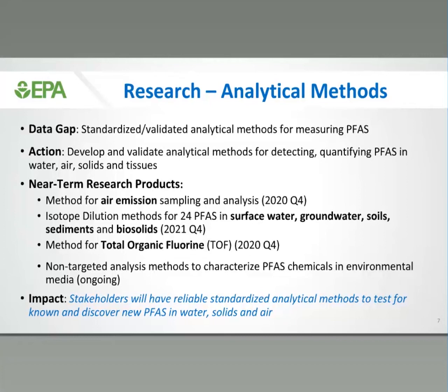I mentioned earlier the isotope dilution method. This is a collaborative effort with Office of Research, but also the Office of Water and the Department of Defense that's actually undertaking a lot of the multi-lab validation. In this method that we're looking at right now, the CWA 1600 method, that'll be applicable to non-potable water, so things like surface water, groundwater, wastewater, but also some water-related solids, including sediments and biosolids. So it'll be a very broad and applicable method. The single lab validation should be finished in the next few months, and then the multi-lab validation and the final publication in the latter part of next year.